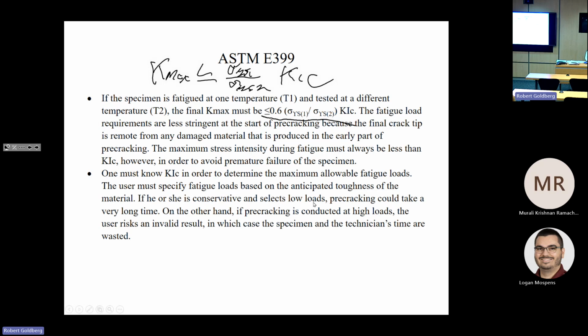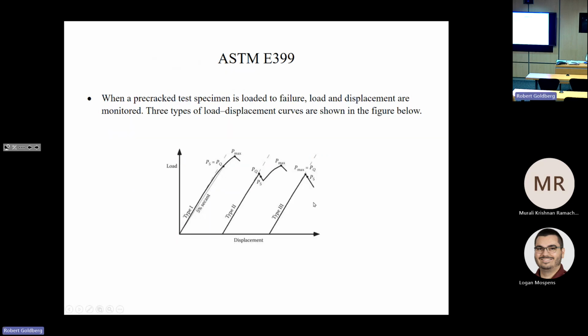So it's one of these things where you want to strike that balance between being conservative enough to ensure that you have a valid test, but not so conservative that it takes forever to get your specimen set up just so you can do your testing. Now, when the pre-crack test specimen is loaded to failure, you monitor your load and displacement,